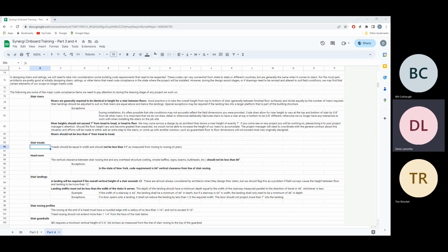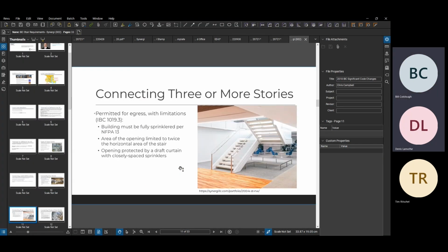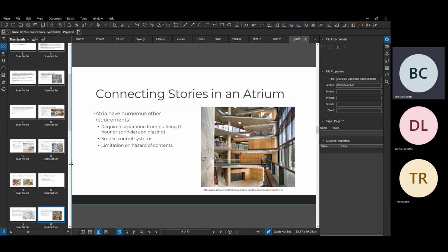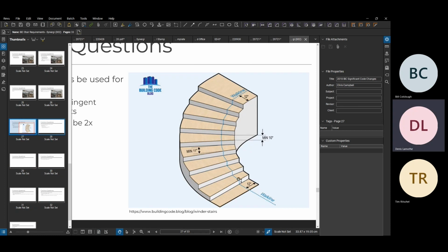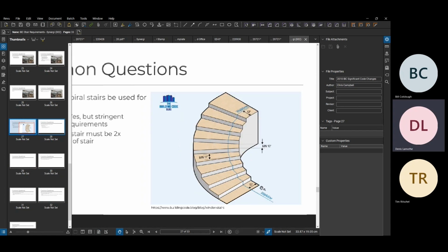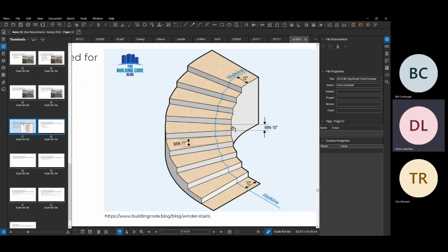exception to that, and I'm trying to find the file here. And of course, I'm having absolutely no luck with that now, but it's in here somewhere. Let me just pull up, you would have seen that at the building code seminar. Circular stairs, it's measured a little differently because of the shape. Center of walk. Exactly. There we go. So center of walk is still should be 11 inches. The absolute minimum at the end should be 10 inches.